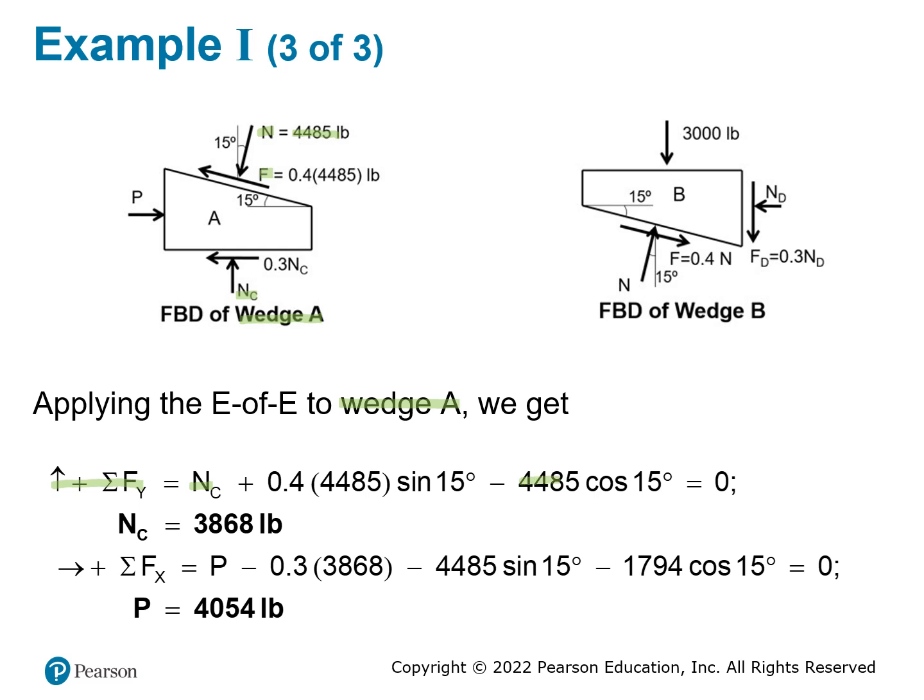So which is this one here, and cosine 15 degree, because this is going to be the adjacent part right here. And then you have the friction force here, and the y component will be the sine 15 degree, and it will be 0.5 times the n, so that is your y direction.